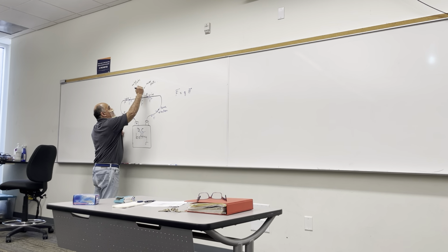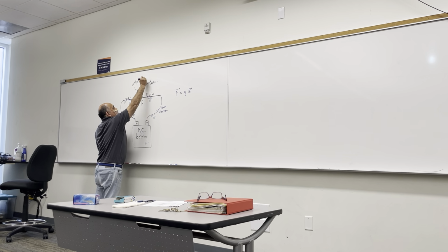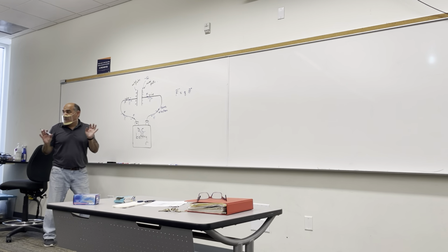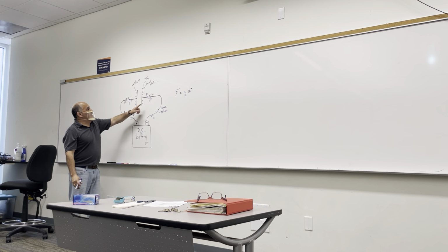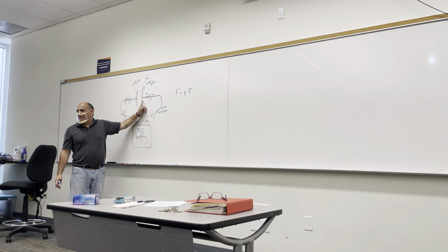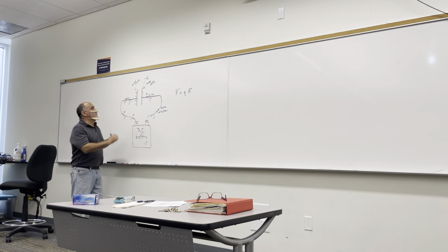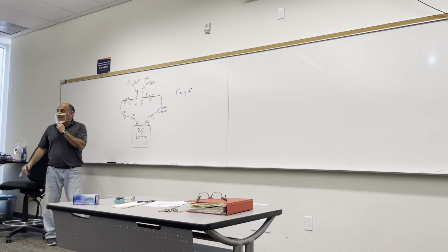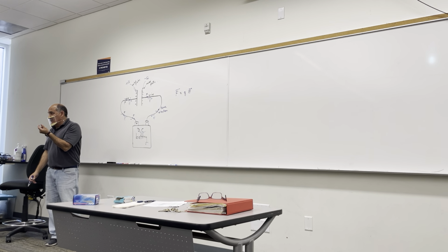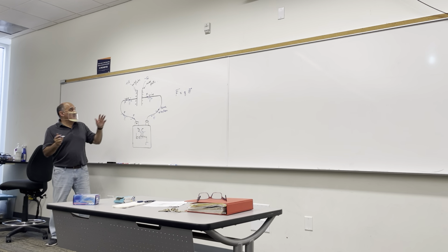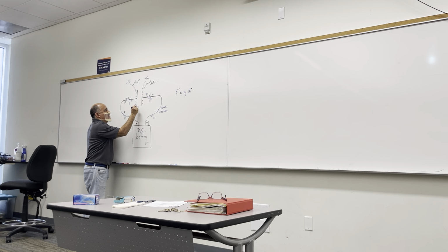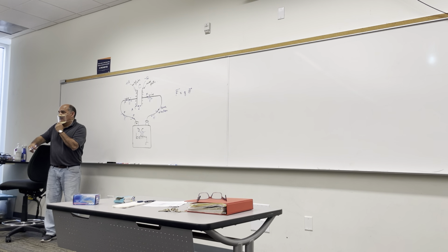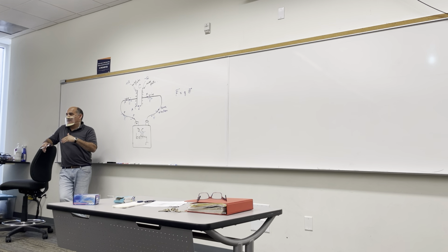And remember, this will become negatively charged, let's say minus Q, right? Now, if 15,000 electrons arrive over here, 15,000 electrons left the other plate. So then the charge on this one will be plus Q. And now you have two conductors separated by an insulator that's charged. And because of the area of these plates and the separation between them, these two conductors constitute a capacitor with a given capacitance.